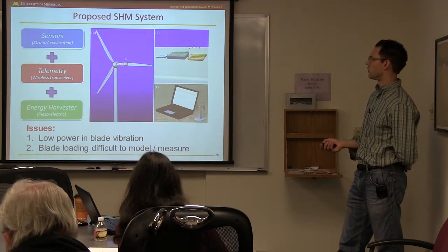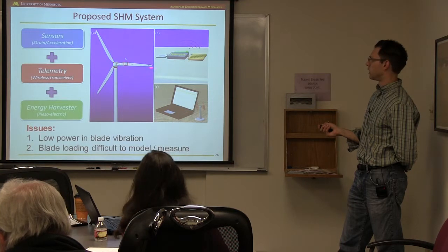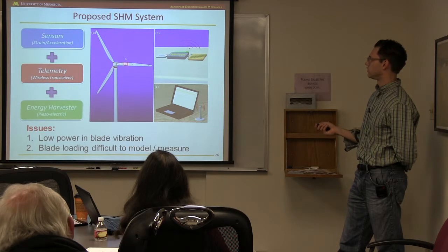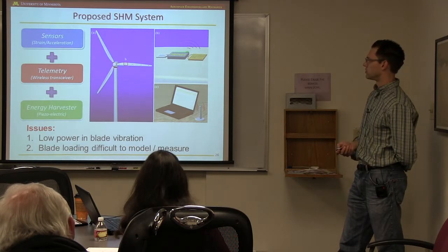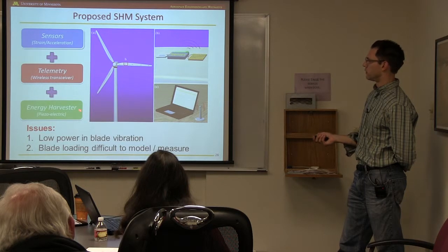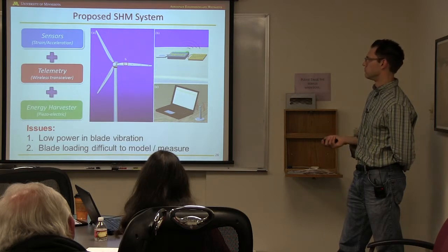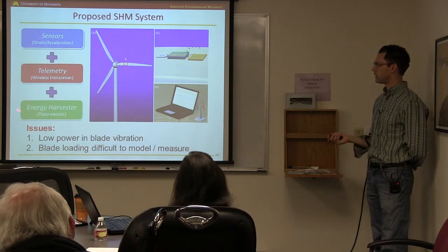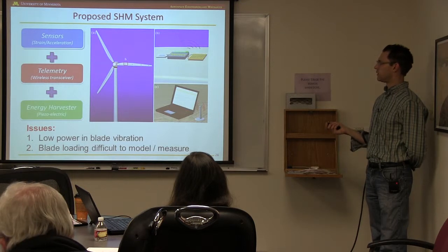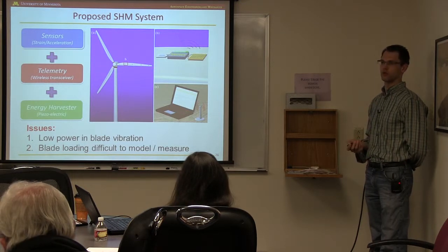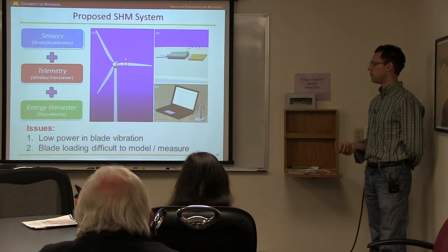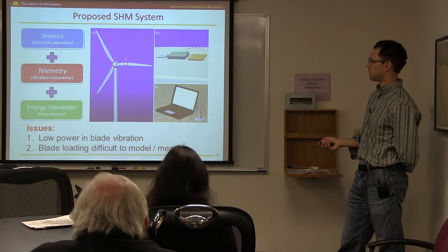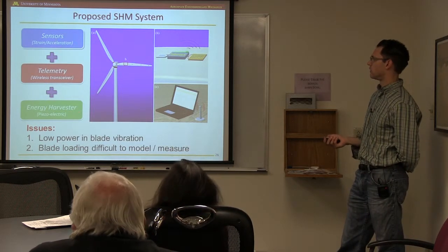So here's the concept that we were thinking about. Imagine you place sensors along the blades. They could be strain sensors or accelerometers, and you have some telemetry, some wireless, so you don't have cables for transmitting the data, and then you have some energy harvester. We've been looking at piezoelectric, but maybe you could look at solar or something else. So you've got something that can generate power at the blades. Now, how are you going to generate this power? In our concept, the blade vibration is what's causing the structural loads, but you can actually use that blade vibration to power the sensors as well. So we're going to try and harvest the vibrational energy and use that to power the sensors.